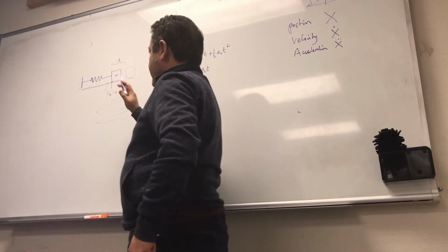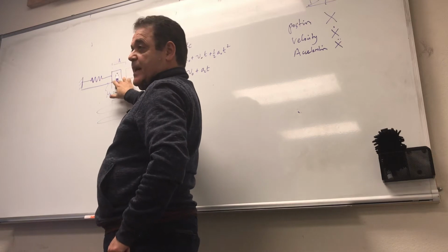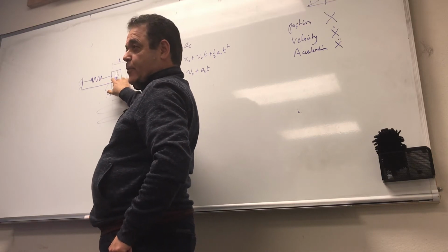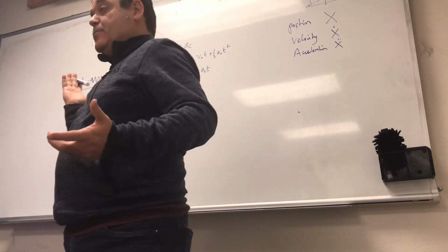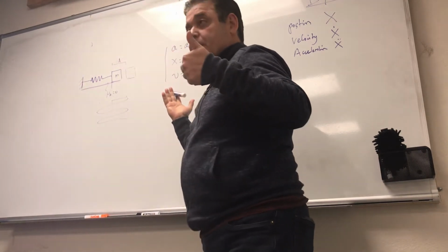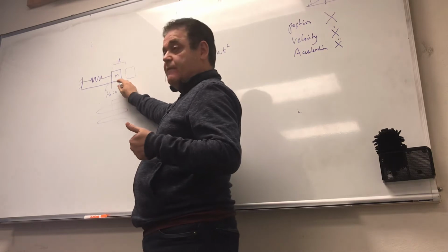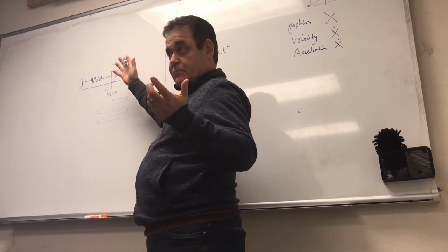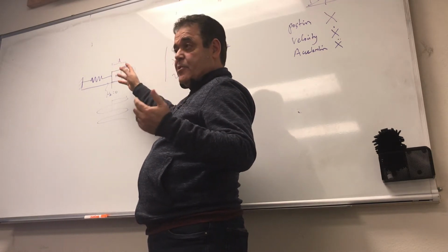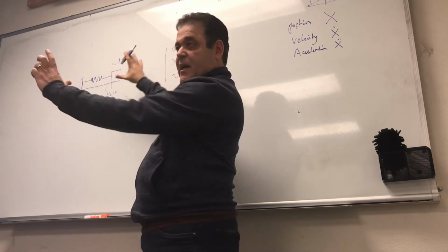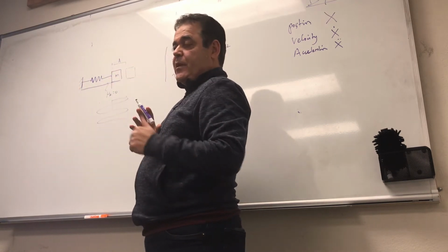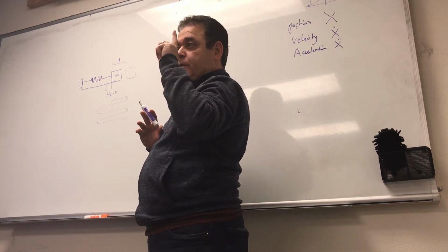But to describe this dynamic system, remember what I said before: you have to look at how many masses you have. How many masses do you have in here? One. So for each mass you have X position, right? If I know at every given time where X is, I know how the system is configured. That's why it's 1 degree of freedom.